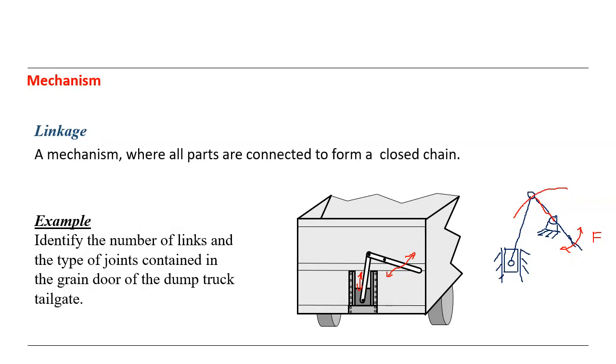Circular motion, let's say. The circular motion will move on this circle with this radius here, radius R, and this link between the slider here provides the linear motion for the slider. So the slider will move up and down like this, and we can open the door and close the door.